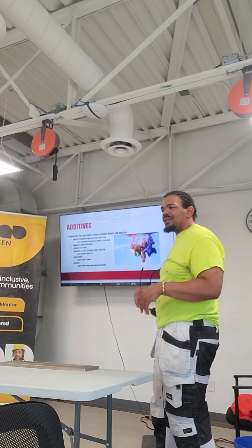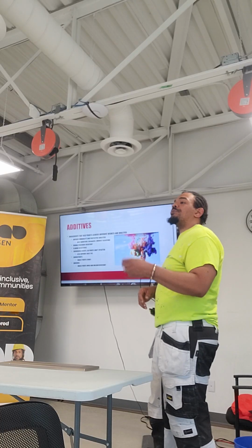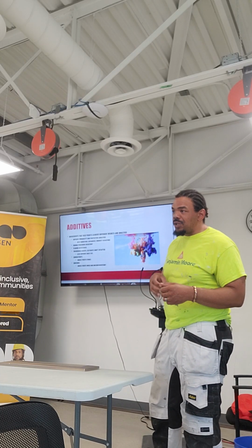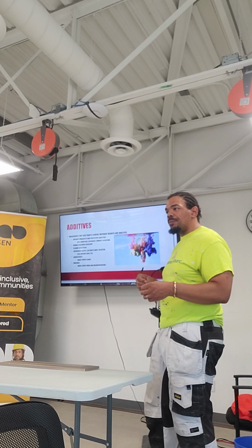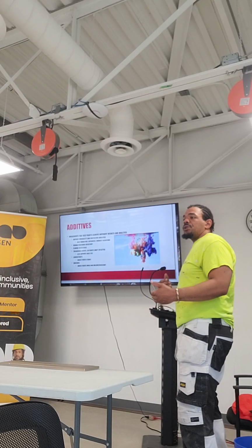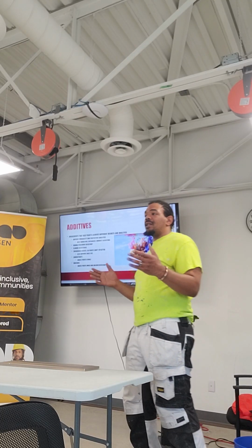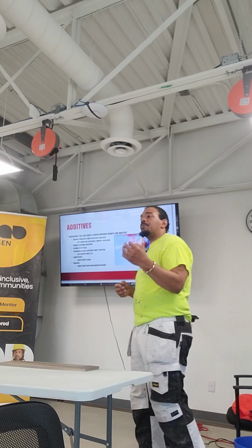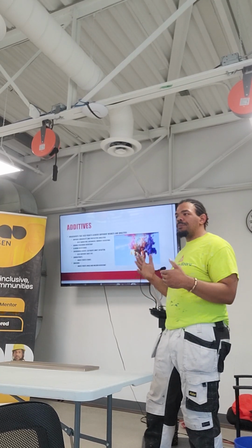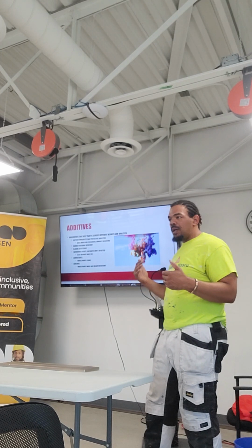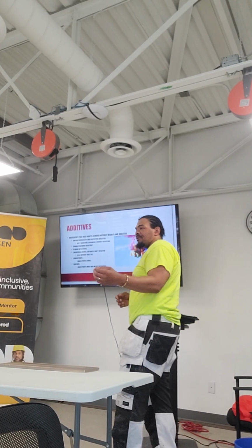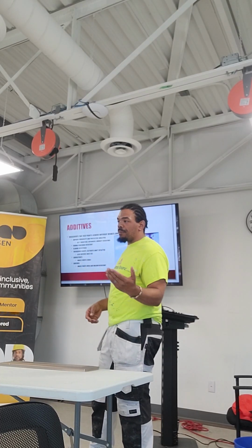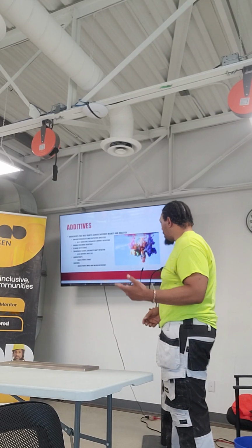I went and did a little research. That's a rust inhibitor. The reason you may spray it before you apply color is that some paints have that additive built into them, and others don't. So you may be in a situation where you need a rust inhibitor primer, and you apply that first, and then you put your top coat. Some primers and top coats already have rust inhibiting additives built into them. But if the material you're using for your top coat doesn't have one, you have to spray it beforehand. So that might be a good example of why that might be happening.